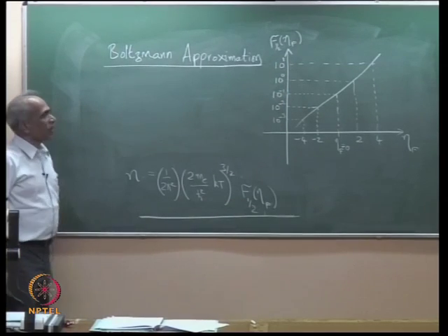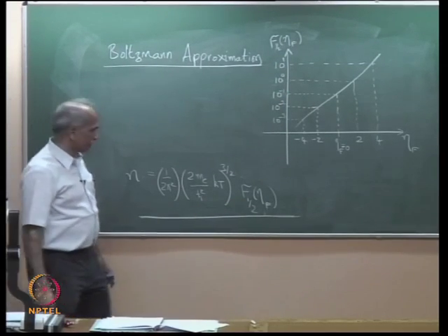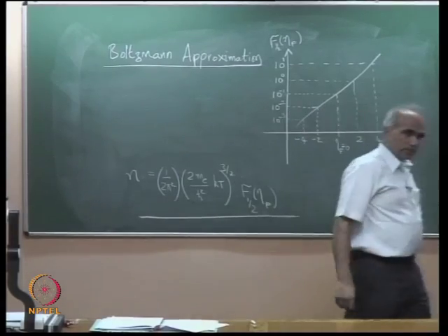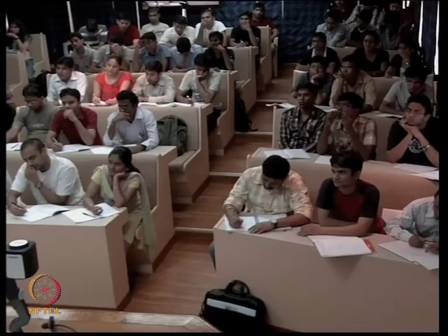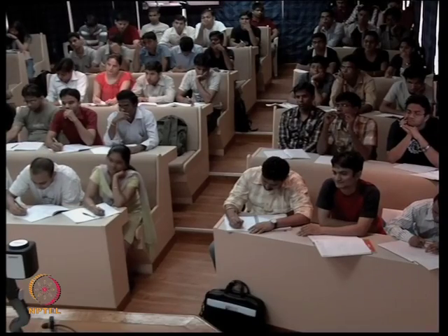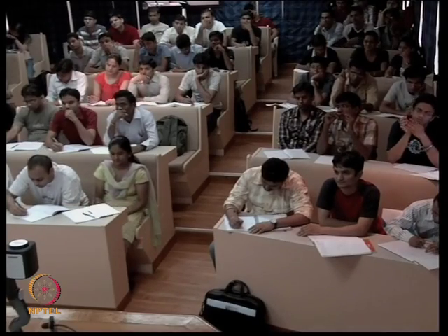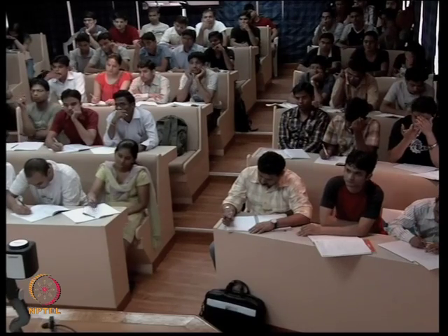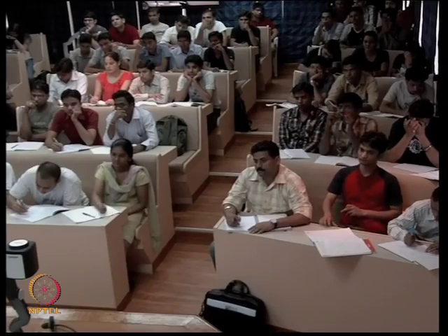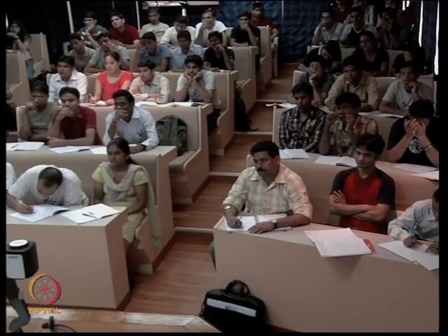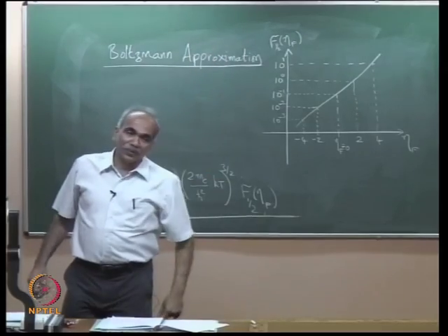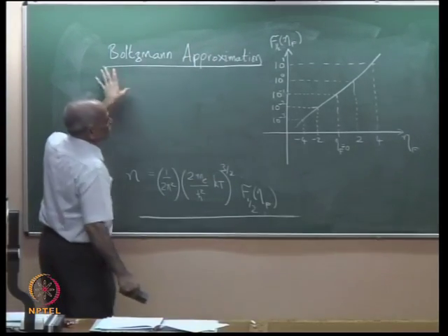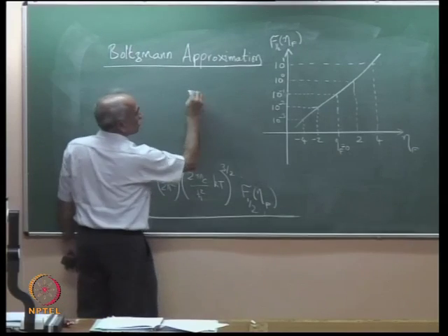Yes, that's right, because if it becomes 0, then the carrier concentration will become 0. It is 10 power 0. So please make a correction there. If the Fermi integral is 0, then the carrier concentration is 0. And at such a high value of eta F, if that becomes 0, then yes. So for the Boltzmann approximation, please correct that.